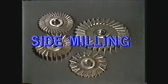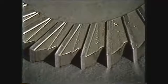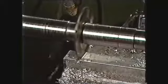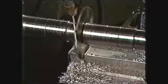Side milling cutters are used to machine steps or grooves in a workpiece. These cutters vary in width from 1/4 inch to 1 inch and come in a wide variety of diameters. The teeth of these cutters are arranged in either the straight or staggered position and are also sharpened on the side. To cut deep slots or grooves, use a staggered tooth side milling cutter. This kind of cutter provides more chip space at higher speeds and feeds than the straight tooth cutter.